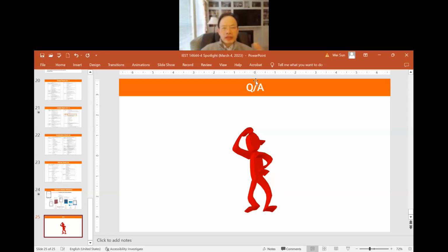And also some key major equipment. And also the activity level of personnel: sitting there, minor body movement, still sitting but moving an arm around, slow walking, or heavy activity. All these activity levels generate different levels of particles, and the references provide more data for that. They typically give you a range, so you can pick some data.